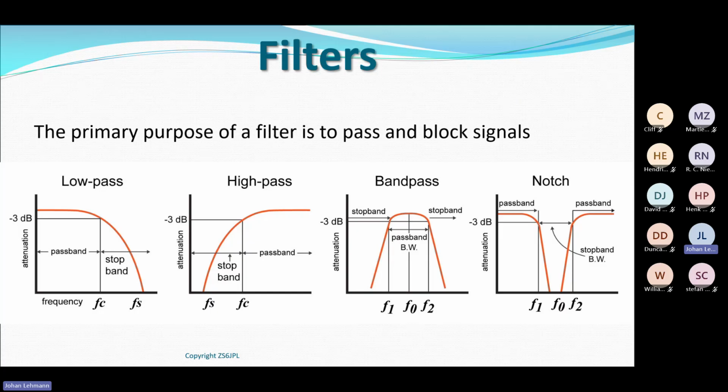And then the other one, which we will discuss in a lot more detail when we do electromagnetic compatibility later before the exam, is called a notch filter. So if I select a design frequency, I can set it so that anything lower than the design frequency is passed, and anything higher than the design frequency is passed, but at the design frequency, I'm blocking it, I'm notching it out. So those are the 4 types of filters which we're going to use in our radios and in our equipment moving forward when we get our licenses.